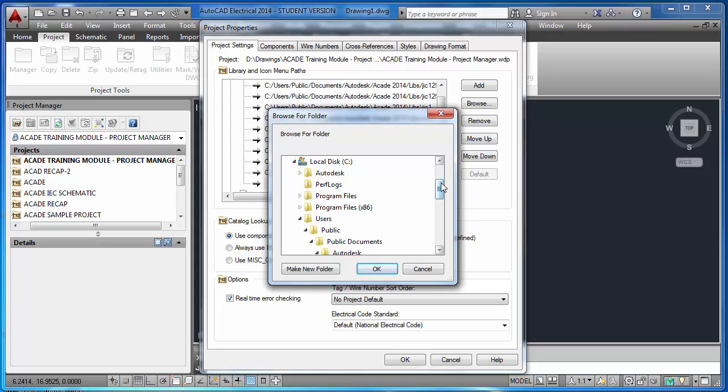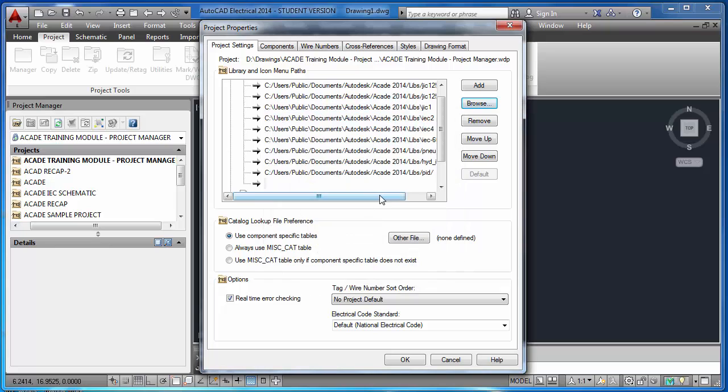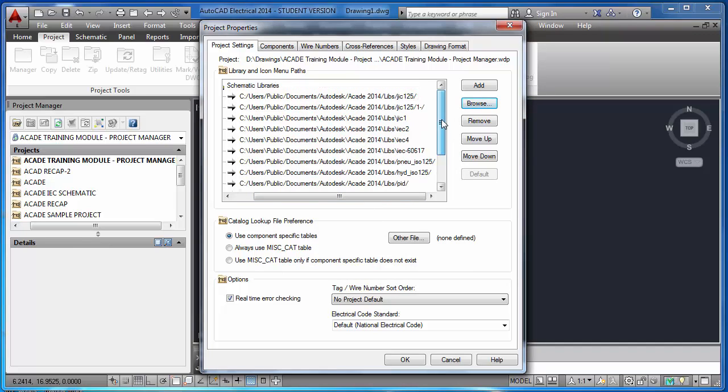Once you become a master of this art, you can of course do a lot of settings here. So my intention is that this is the path AutoCAD goes and reads. So if you don't find some library here, don't worry, add, browse to the library, select it, that's all.